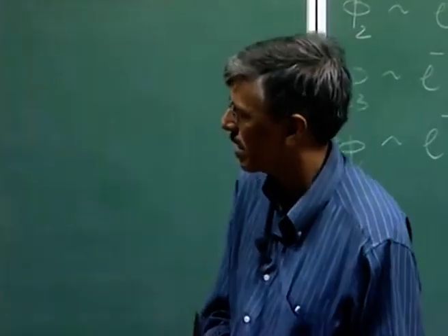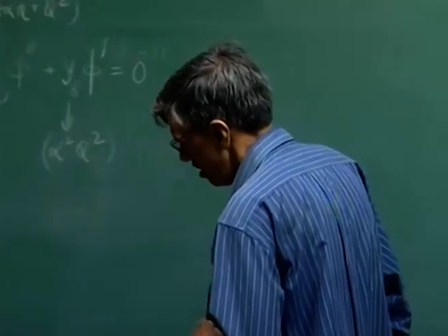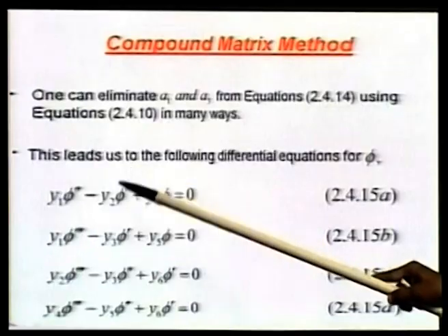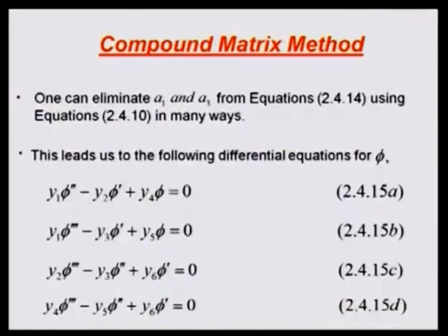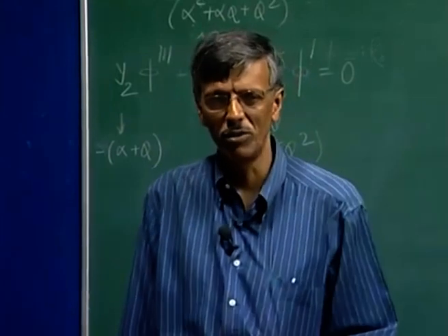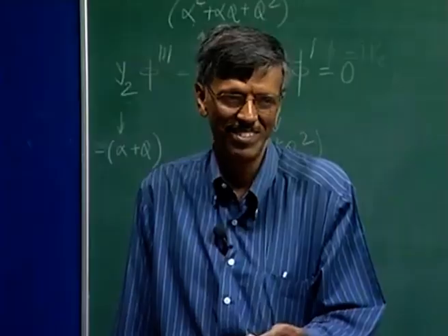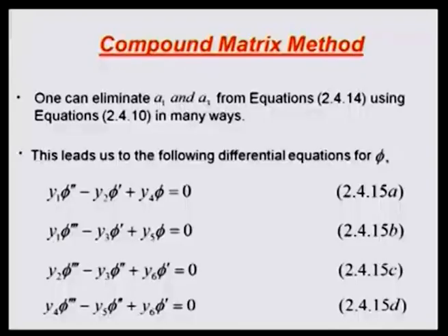Well, people have made all kinds of observations saying that okay, if it is indeterminate at the wall, so what, you do not do that. You actually solve the Orr-Sommerfeld equation itself by one step or a few steps, and then you start off using the first equation. It is not elegant, because the problem of stiffness, growth of parasitic error do remain.